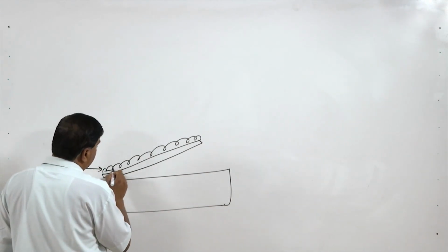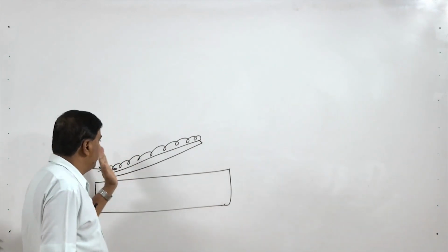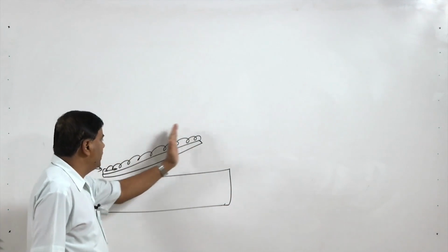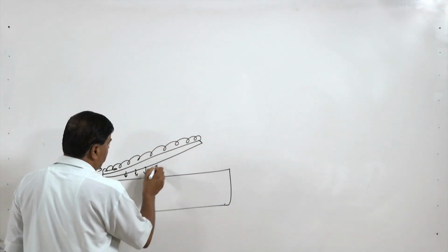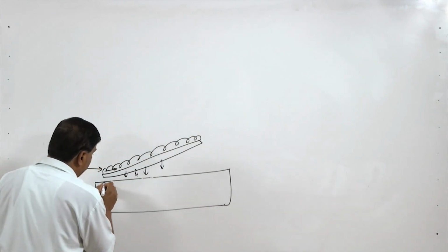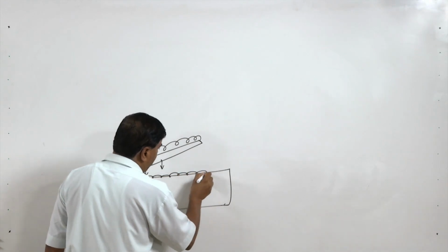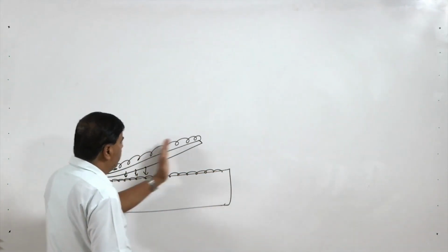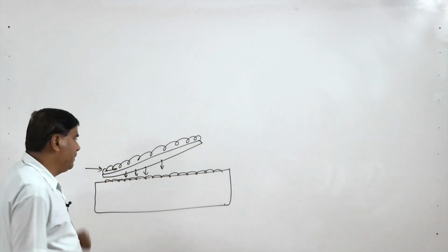So, the flame front or the explosion will be moving from one end to the other, pushing the plate sequentially down, and so the bond will be formed also sequentially from one end to the other. Impact in one go of the entire prime component plate with the bottom one will be avoided.